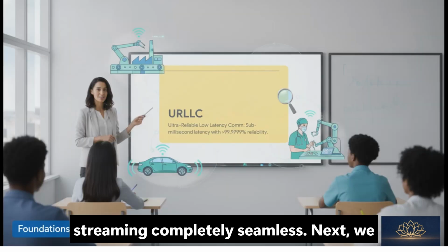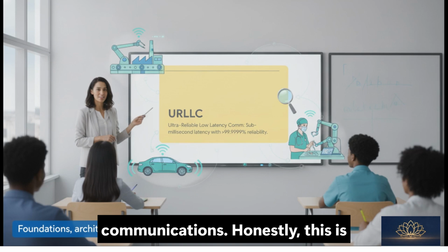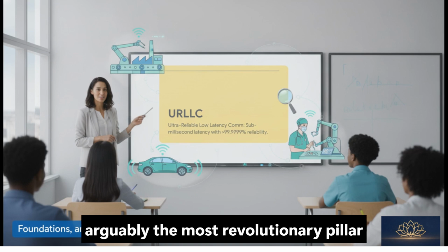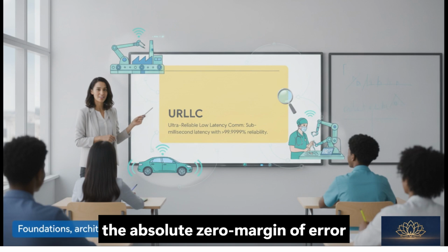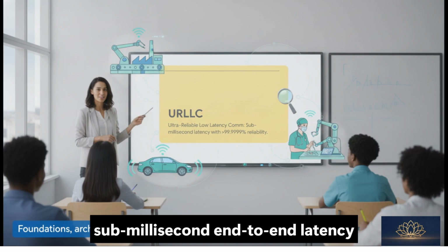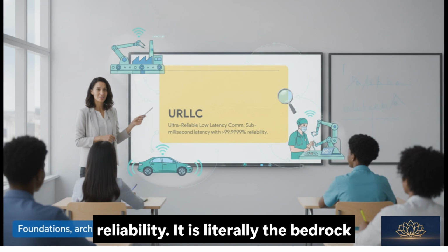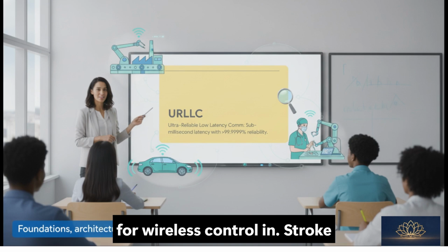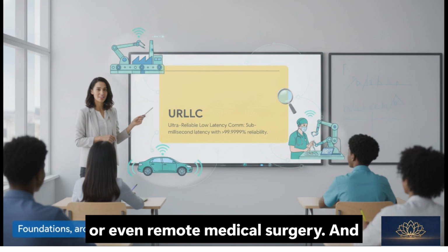Next, we have URLLC. Ultra-reliable and low-latency communications. Honestly, this is arguably the most revolutionary pillar for enterprise and industry. It provides the absolute zero margin of error connectivity required for critical control. We are talking about sub-millisecond end-to-end latency coupled with greater than 99.9999% reliability. It is literally the bedrock for wireless control in industrial manufacturing, autonomous vehicle safety, or even remote medical surgery.